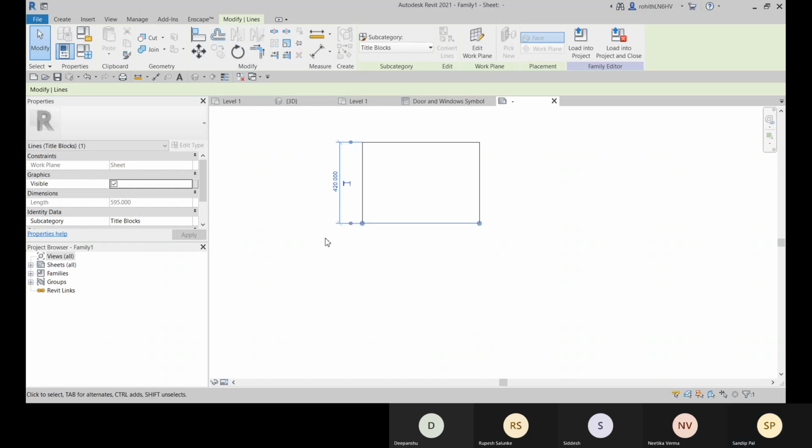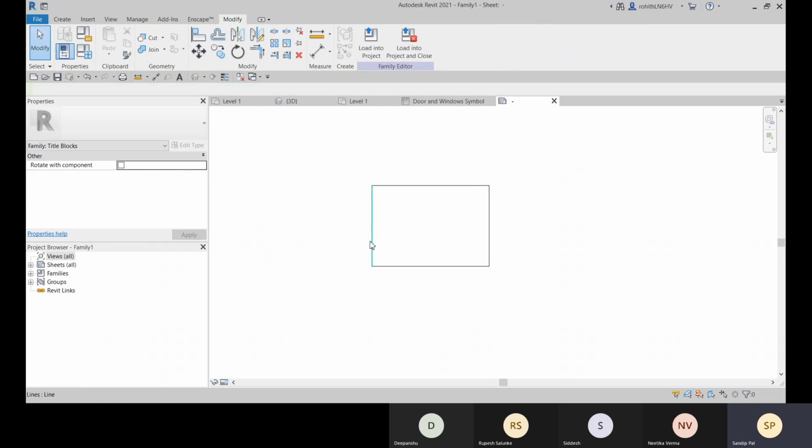Enter. And this is your A2 size. Okay. So this way you can get all the paper sizes to A4, A5, you can easily remember. So just remember one paper size value, that is A0 841 by 1189. And from that, you can get all the paper size values.